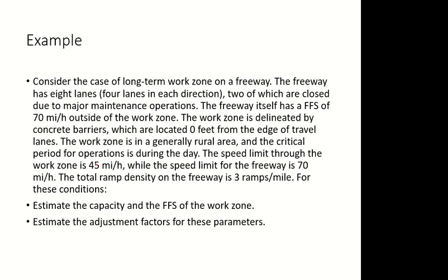2 of these 8 lanes are closed due to a major maintenance operation. So it's a long-term work which is doing major maintenance. Out of 8, 2 lanes are closed. The free flow speed outside the work zone is given. Work zone has a concrete barrier. It is 0 feet from the lane. The barrier and the lane are at the same point. So the barrier is at the edge of the lane.